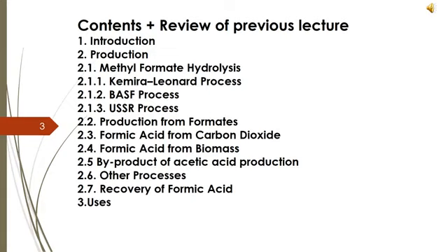If you recall, after the main reactor D there was E, after E there was F, and after F there was G. But we directly fed the materials, the products and reactants from the flash tank, into G rather than into F. There is no direct contact between E and F. So we fed the materials into G, and their vacuum distillation took place, and from that distillate, methyl formate and methanol are separated in the recycle column F. So F is the recycle column.